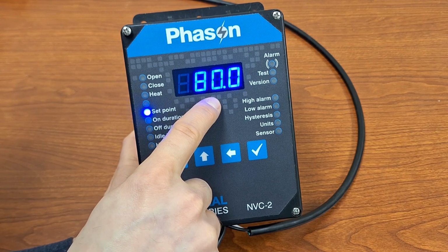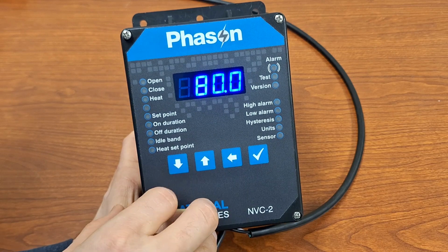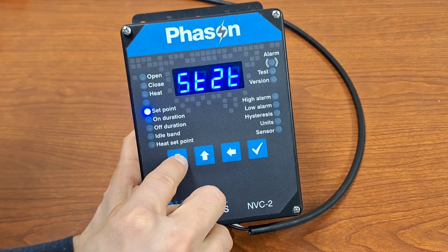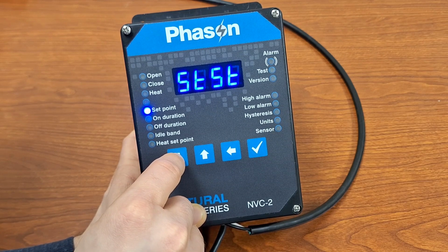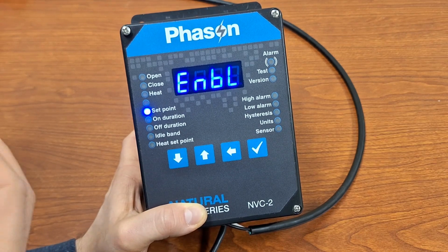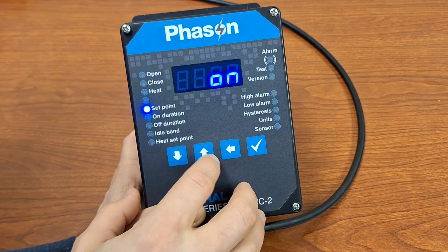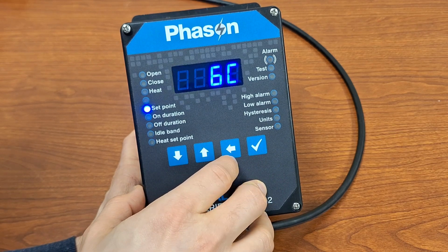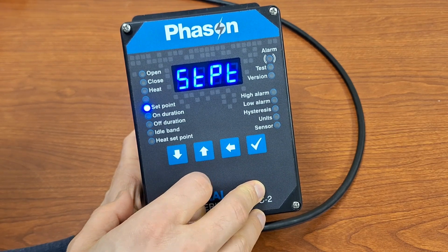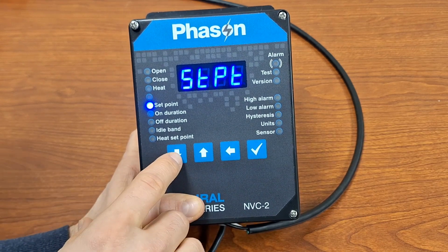We're going down to 80 degrees. Same thing, you can adjust it up or down. Go back, and you can keep going. We've got step 3, step 4, 5, and 6. So up to 6 steps and 365 days that we've got on here. For now, I am actually just going to disable this growth curve and have it running off of the set point instead. So that is how you set up your growth curve and your set point.